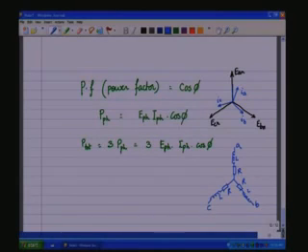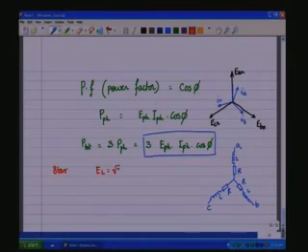So, in such a case, the total power of all three phases put together is given in this fashion, and still the relationship, let us say in the case of the star, we would have E line is equal to root 3 E phase, and in the case of delta, we would have I line equal to root 3 I phase.